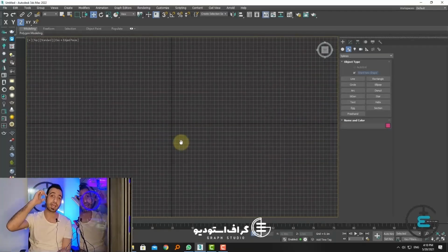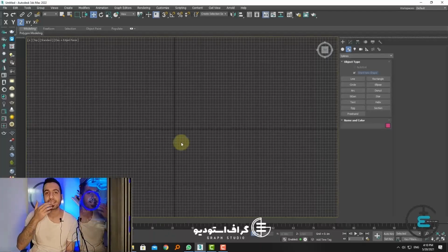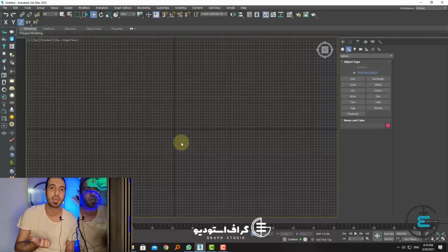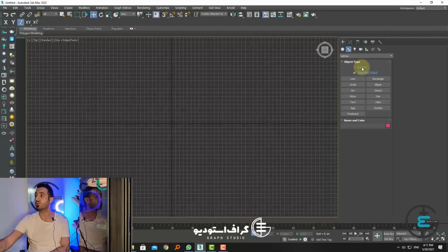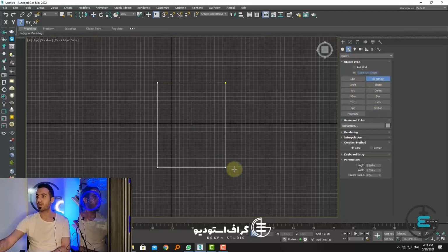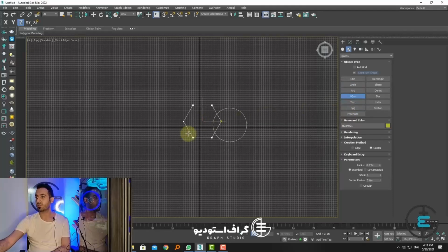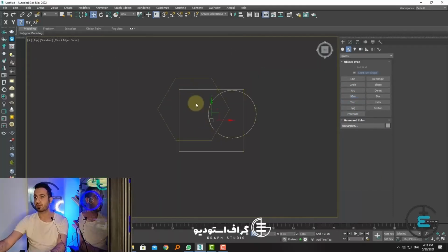They are all selected. Now, in order to combine these together, I activate ProBoolean and select them all. And now you see that the Boolean options are active. I put it on subtraction, for example, and if I hit Boolean, you see it comes and performs the subtraction from this. Or, for example, I put it on intersection. I say intersection, and this comes and performs the operation. You see it performs the sharing for us.